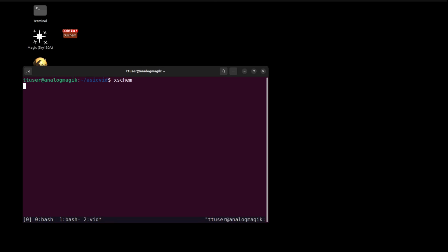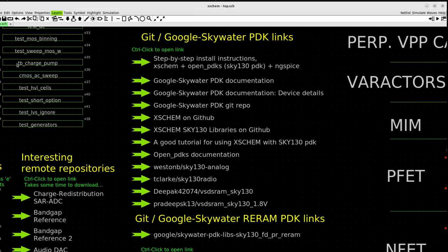Here we're in the world of the tiny and the rules are different. Everything's optimized for making MOSFETs and you're going to do a lot of that. So you can create a lot of different kinds of those, and used intelligently, your circuit will behave well without consuming much power, which is what CMOS is all about. When you open up xschem in the VM, you get a nice overview of everything in the Skywater PDK, the process we're using to make these chips.